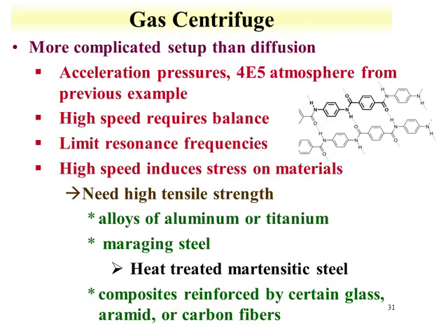While the gas centrifuge system has this high separation factor, it's much more complicated than the diffusion setup. This has to do with the moving parts involved in the centrifuge. You have large acceleration pressures, and the fact that these centrifuges are moving at high speeds requires finely balanced centrifuges. And you also have to design them so resonance frequencies are limited, so when they begin to spin, vibrations do not occur. And these high speeds induce stresses on the materials that weren't necessarily found in the gaseous diffusion system.